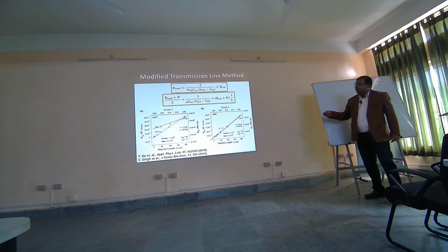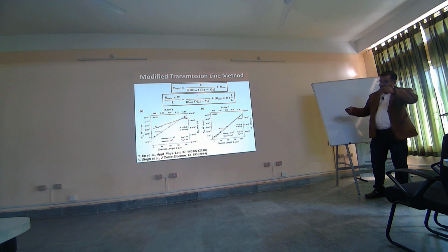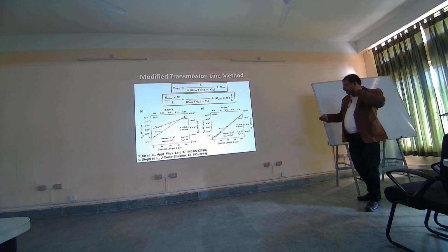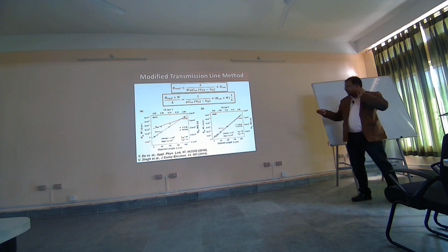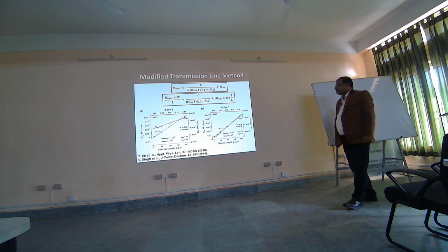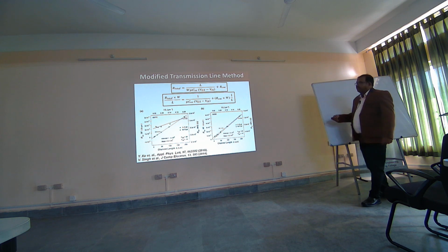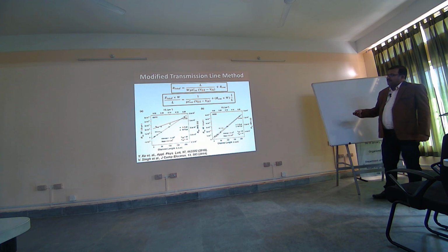Because of these variabilities, in the graph that we are plotting, sometimes the data points are not well aligned, and if we try to fit a line, the intercept sometimes even comes out negative, which does not have any physical significance. So what we did instead is we normalize this by writing R total into W by L, so we multiply W by L all across.